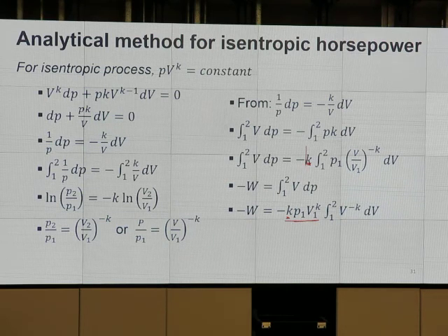What about this K? This K comes from here, right? I take that K out from the integration. This means that K, the K of gas, is a ratio of Cp over Cv. It is a fluid property. So I assume that it is constant from condition 1 to condition 2. So when I move the piston, even though the gas gets compressed more, K stays constant.